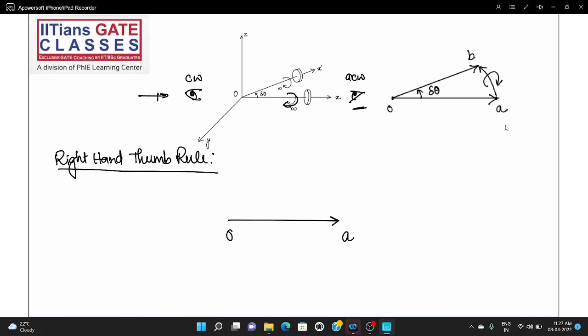Now after some time, this angular velocity is also rotating about another axis, that is OZ, that is the axis of precession, right? Say in a small time delta t, the axis of spin rotated by angle delta theta. Then we can say the angular velocity of precession, omega p,